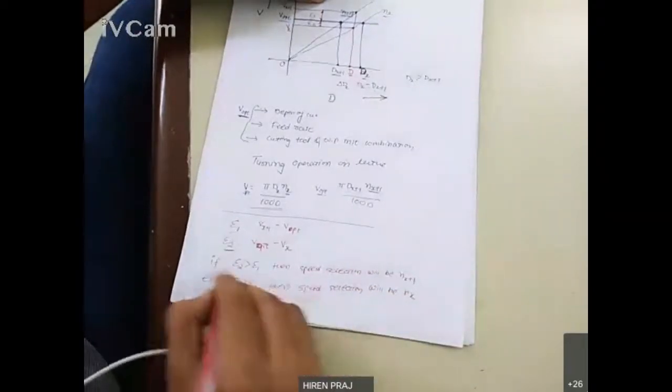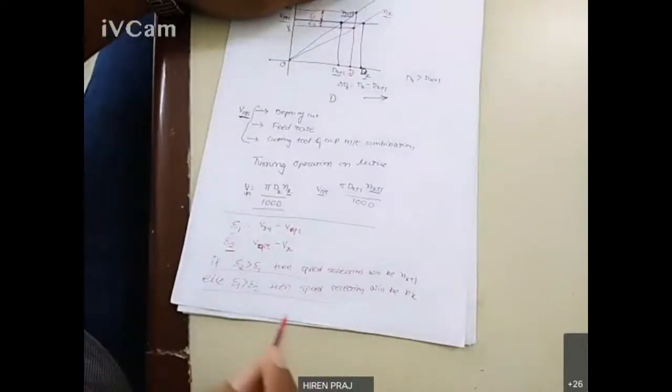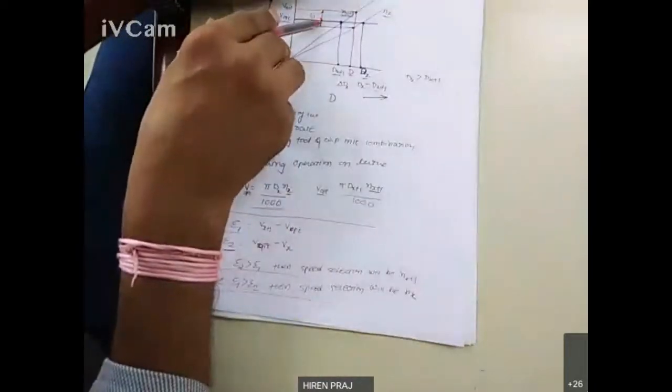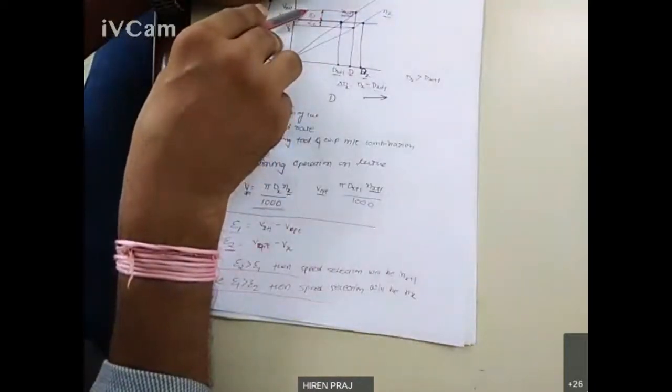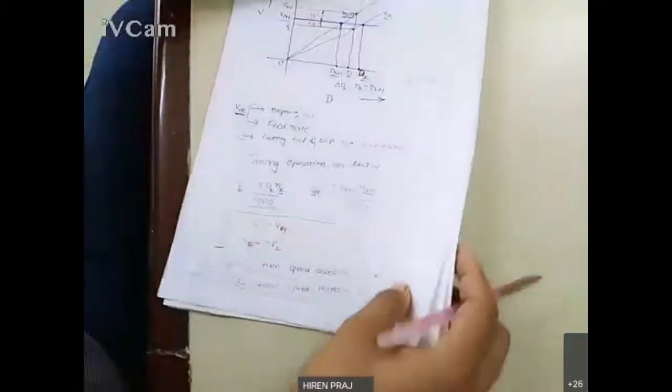So based on this we will select any one speed so that we get less loss, because loss is the difference between the actual cutting speed and the optimum cutting speed, right? So based on this we will select any one speed, but let us consider the maximum case.